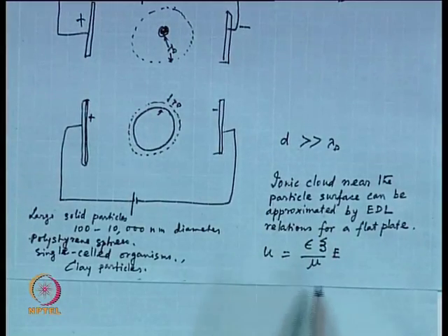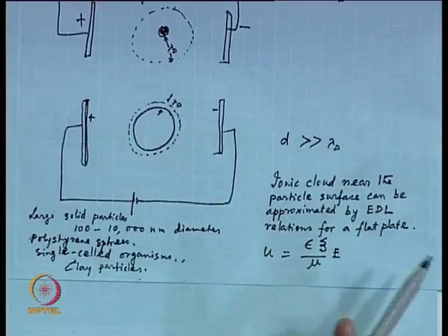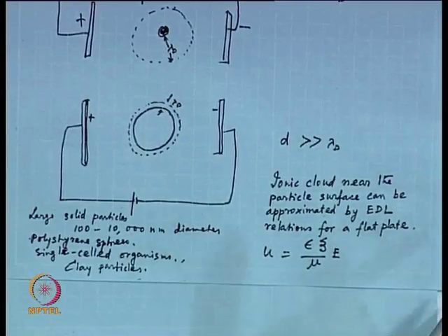Do you recall this expression? We have used this expression in connection with the electroosmotic velocity UEO. We have talked about this expression before. You remember we have that 1 minus cosh something divided by cosh of h by 2 lambda d. So, that expression was there, and we said that for a major part of the channel this is the velocity that is prevailing. So, this was UEO, that time we referred to this as UEO, the electroosmotic velocity.